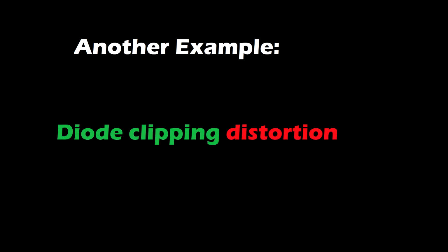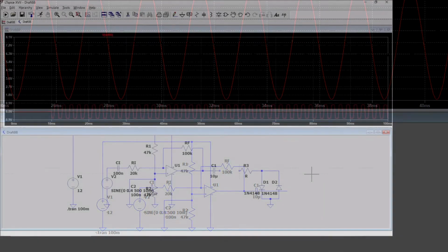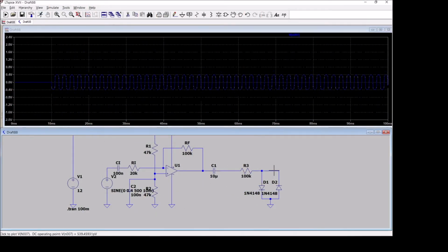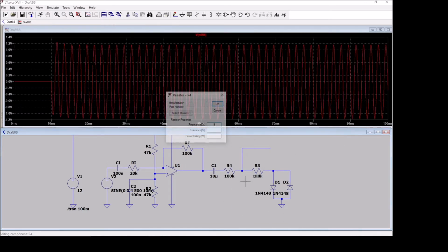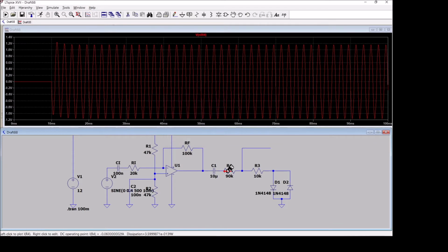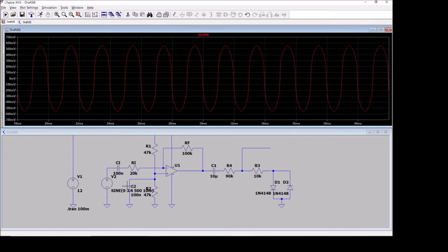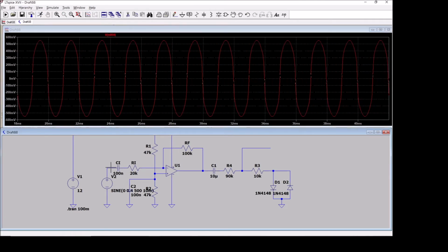Why don't we add real distortion to the circuit? We can do this with a diode clipping circuit. Of course, you would add a second inverting amplifier after this to recover the clipped output voltage. Maybe a buffer after this too. With this we have created a guitar pedal. Congratulations! I look forward to see what distortion designs you come up with. Tell me about it in the comments below.